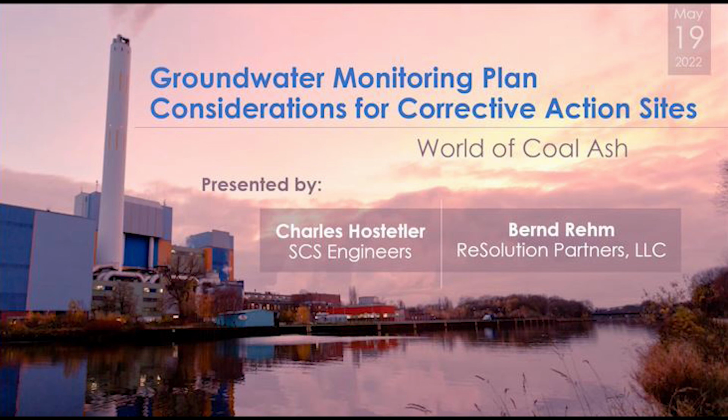Might that include, for example, getting air down into the aquifer? It might. It might also involve putting a flow-through adsorptive bed that has specific redox characteristics. We've gone the other way when we've been looking at chromate. So you might put up a reducing subsurface barrier, and when groundwater flows through that, it takes the chromium-6 and turns it into chromium-3, which is much less mobile. So there's lots of different things you can do to oxidize or manipulate the redox state of the subsurface that are known to be effective.